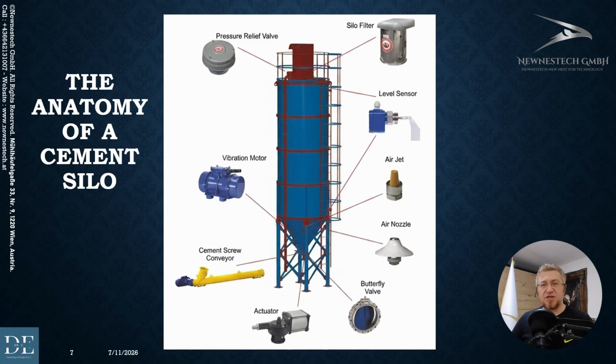Because the silo is filled via high-pressure air streams, we must safely vent the entrapped pneumatic air into the atmosphere. However, this escaping air carries a dense cloud of fine cement dust. To prevent environmental contamination, an air filtration unit is installed directly on the central axis of the roof deck.